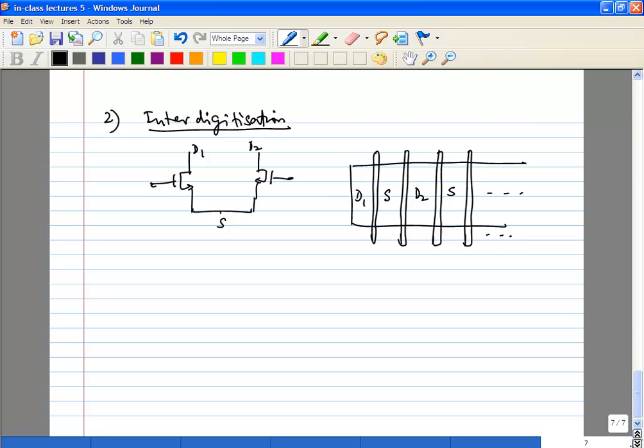Here, if two transistors, for example, share a common node, in this case a common source node, you may want to reduce the parasitic capacitance at this node. Remember that for the mixer, classic example. If these are the switches, you want to reduce the parasitic capacitance. So for those switches, you're going to share the sources. Drain capacitance, you don't care too much because you're actually having an RC filter for a receive mixer. So you may want to do something like this.